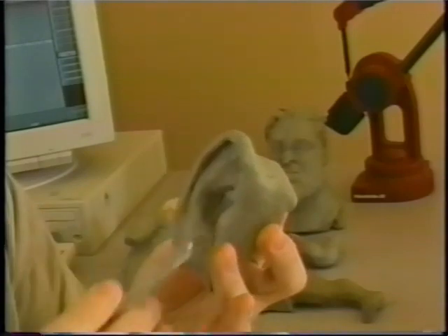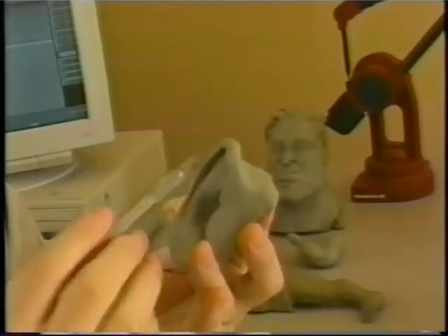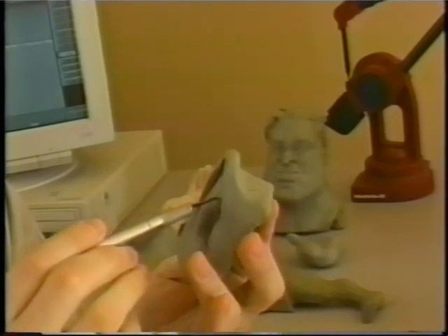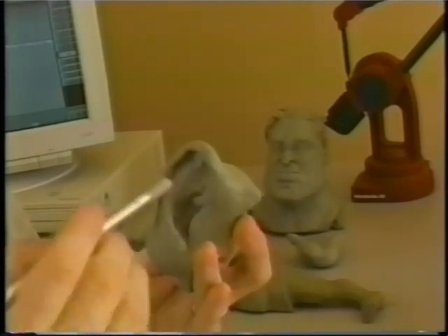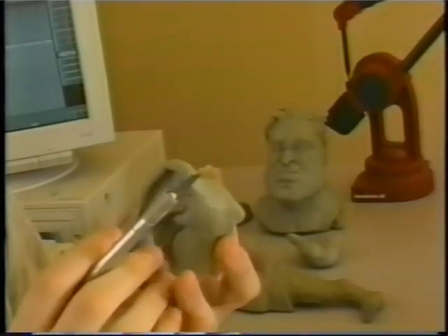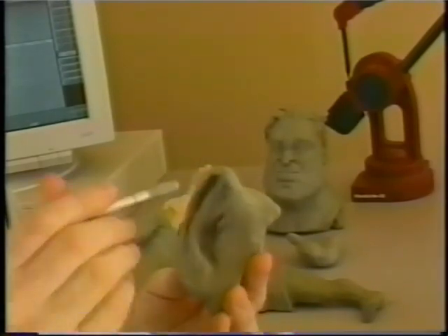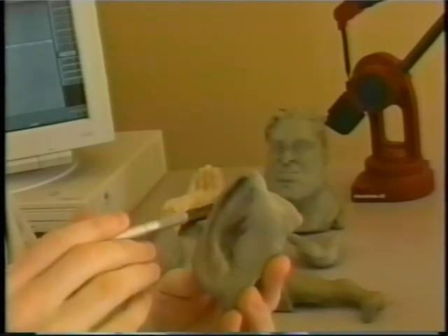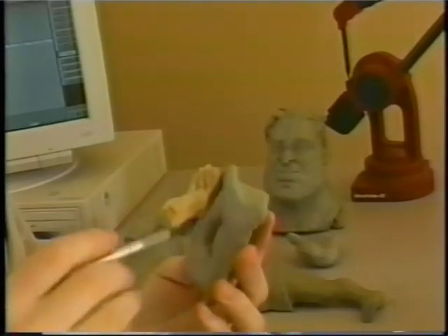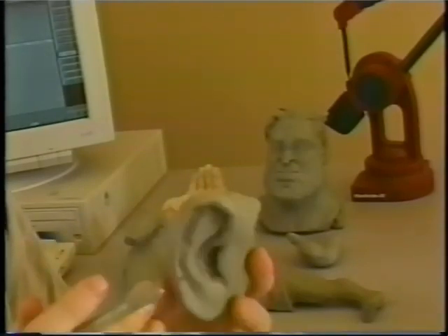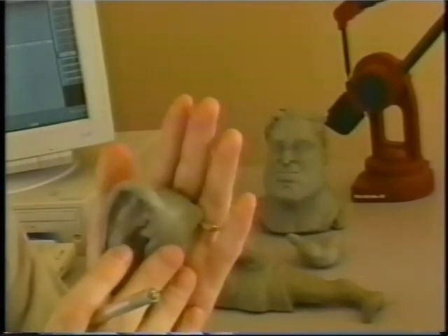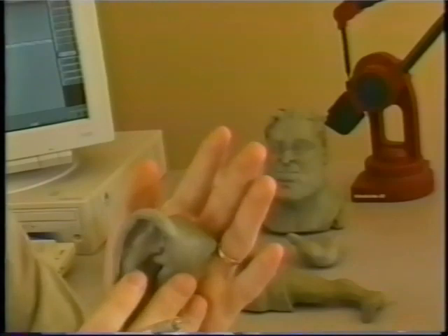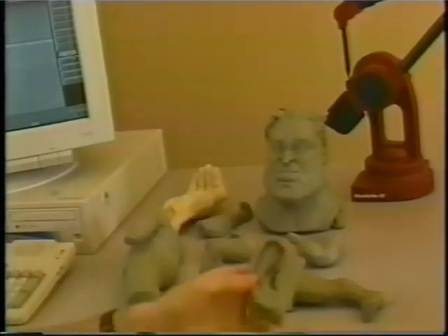Like the ear, obviously very round shape, very complex. What you want is to have the lines in a circular pattern, and that's what I did here. Started actually not in the very inside of the ear, but right here, right there, and then circled out, wrapping in and out, but getting all the detail of a very complex ear, so that one edge would travel all the way around here, and so you'd have a very nice, well-defined ear. The surface connection of the ear to the head is actually quite simple. It's one of the easiest connections because that part of the head is not really very complex. And so this is a good option for ears.